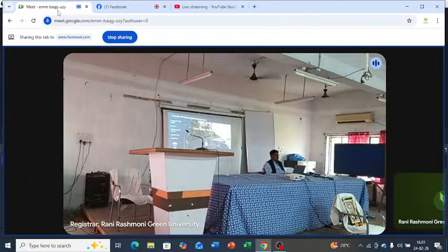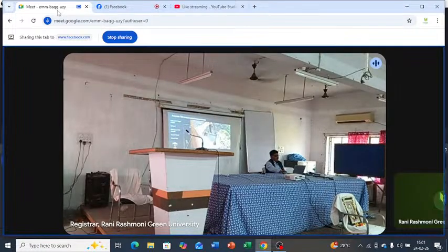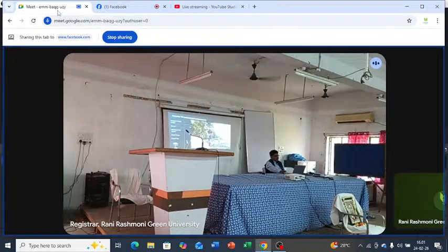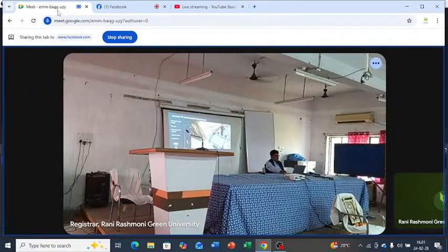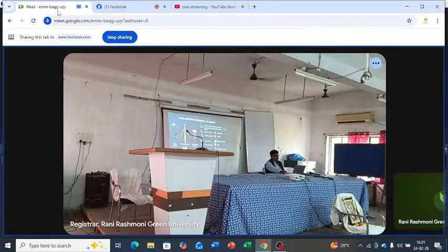This is quite rugged, even though it looks small. The only thing is that we can work with tilt only up to 13 degrees, to get the highest accuracy. So a little more detail on this GNSS: it can be used as an RTK reference, as an RTK rover, as an RTK cold rover or smart cold rover, which can also be used with a motorized rover station.